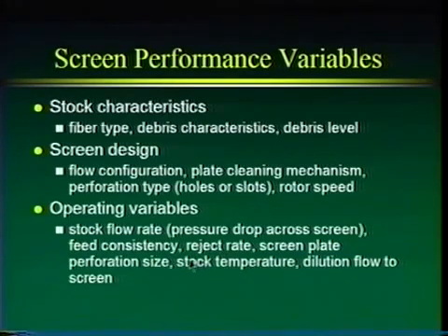It also impacts the softness of the contaminant particles. If we soften those contaminant particles, they may pass through easier. And then there's often dilution flow to the screen. The more the dilution flow, the lower the consistency, obviously, the better the cleaning we get on the surface of the screening plate, and that can also impact our screening performance.